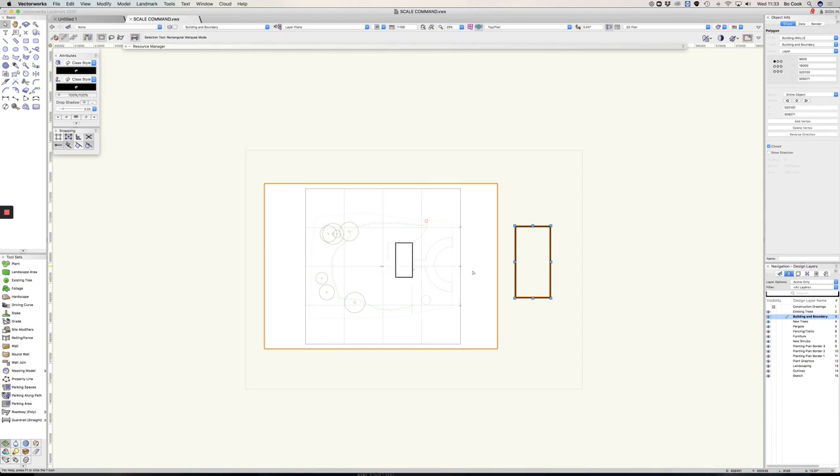to scale from. That might be a scale bar on the drawing, it might be a grid like I've got here. I've got a 20-meter grid drawn on this, or it might be that you've actually measured something on site. So it could be that you've measured a side of a building or a doorway or anything like that. For this I'm just going to show you, I've got a building here, I know what the dimensions of that are. Then I've imported my survey, and the survey is clearly not to the right scale.